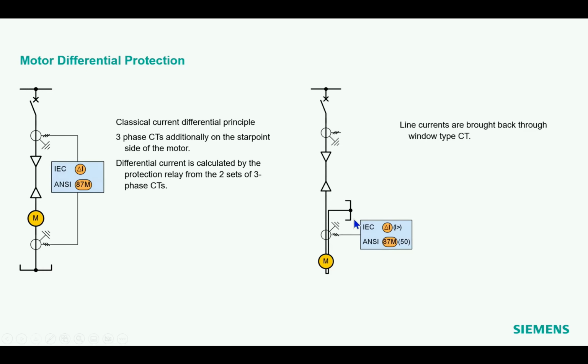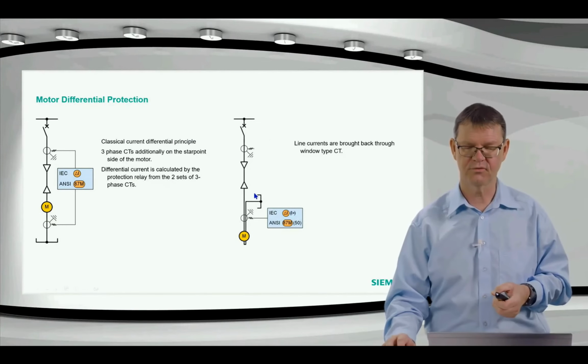What happens in this current transformer is that the currents under normal conditions flow in both directions equally with the same amplitude, back and forth, and then they compensate each other magnetically, because the resulting magnetic field is theoretically, ideally, zero. In reality, it is not, but it is almost zero, so it is a relatively sensitive thing. And of course, under normal conditions during the startup, I will not see really a current flowing here.